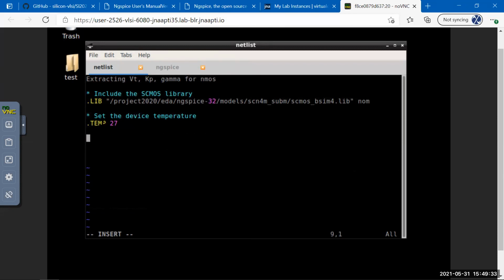Anyone else? Okay, so what should we do next? Write the schematic netlist. Schematic netlist, good. Model. So what we'll do first is we'll extract the parameters from this library. Okay, we'll use the device from this library because this has a BSIM 3v3. It's like got a model which is very accurate to the real device. So we'll use that to extract parameters and then create the model file. So let's skip the model file right now. Let's extract the parameters first. Okay.